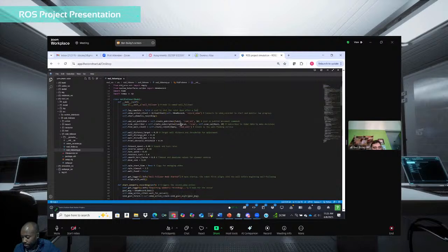And right here, this area is a list of the parameters that I used. These first four are target wall distances and thresholds that I used for movements. Right here are the speeds, like the forward speed of the robot, reverse speed, the turn speed, the recovery turn. So you basically fixed those so that you would know every time it goes forward at that particular speed.